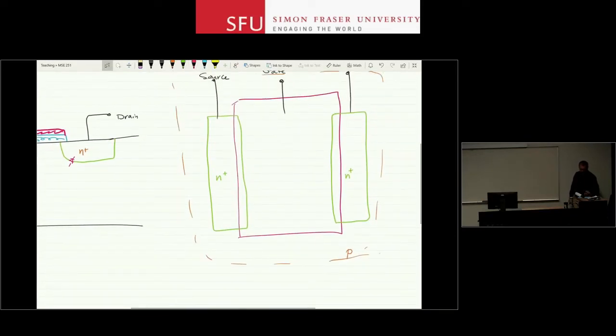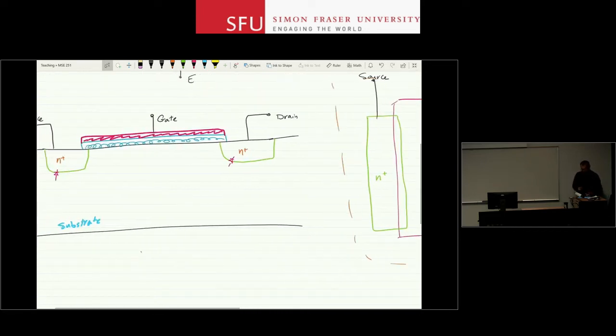So the top view, I have my substrate. I'm looking at it from the top. Two doped regions at the two ends of this, let's say, capacitor, right? But the gate in this device is not connected to drain and source. The gate is on top of a dielectric. Now, so this is the structure.